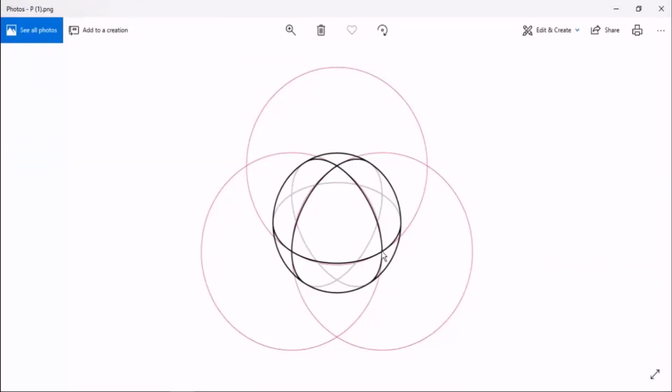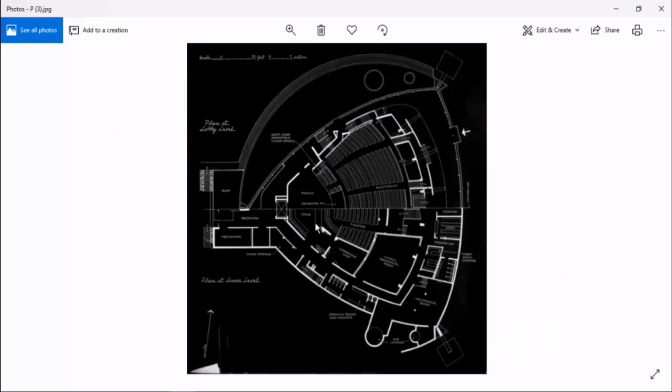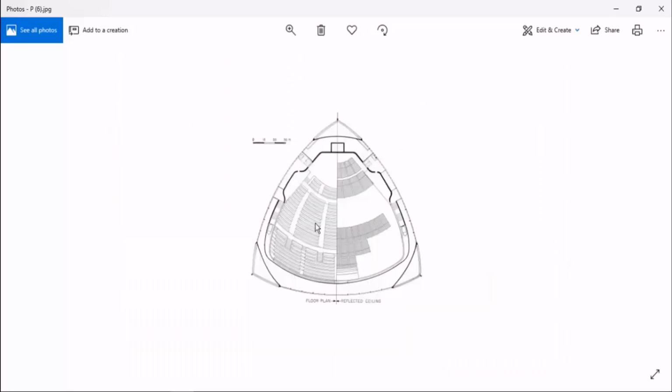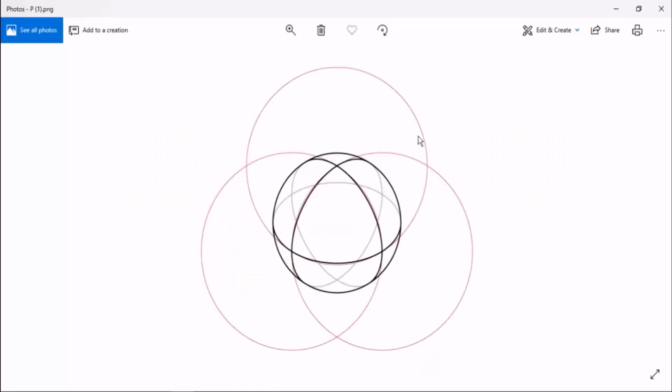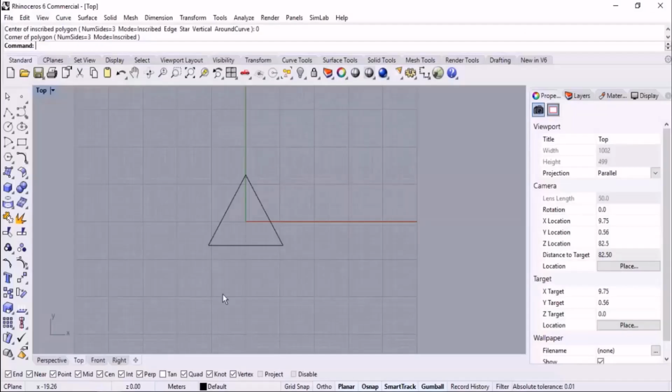But here as you can see from the plan view, we only need this arc as I'm pinpointing in the scene. Do you know what I mean? Let me show you a photo. We only need this arc of the triangle. I mean, here we got the circle that we need a specific part of it. So we can create the circle and then trim the extra part, or even we can sketch the arc, which is a part of a circle that we needed.